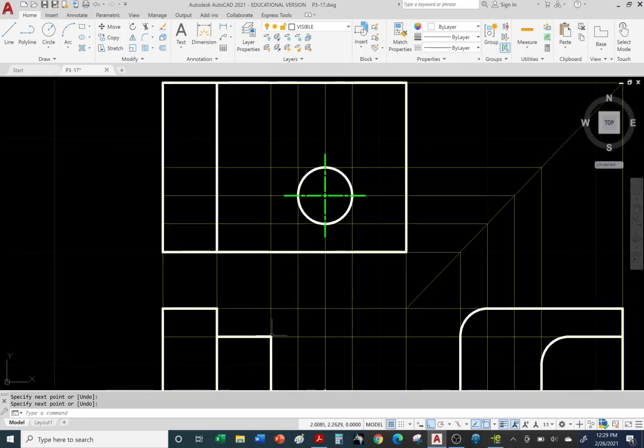Okay, so always when there's missing geometry, lines, curves, circles, always look at the other views and just project across. Okay, so I got this corner. Okay, let's go on to the next corner or vertex. Okay, I'm missing this one. Go straight up. And you're also going to go across. As you can see, it's already there for the right side view. Okay, so things are supposed to line up. Always go to the vertices and then project. All right, so